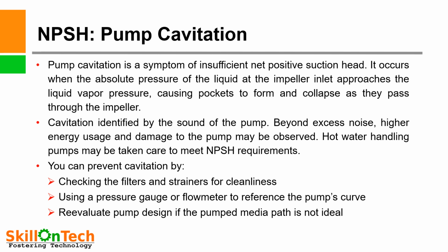Otherwise, NPSH may be a very big reason for the pump vibrations. You can prevent cavitation by checking the filters and strainers for cleanliness, using a pressure gauge or flow meter to reference the pump curve, and re-evaluating pump design if the pump media path is not ideal.